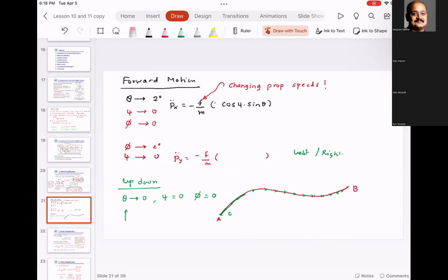But many a times what happens is the pressure is also dependent on environmental conditions, for example, temperature. So you want to make sure that the pressure measurement you get is compensated for temperature as well. For the indoor experiments, we are in a pretty controlled temperature environment, so it's going to be fine. But I want you to keep this in mind as we migrate on to coding, or as we develop